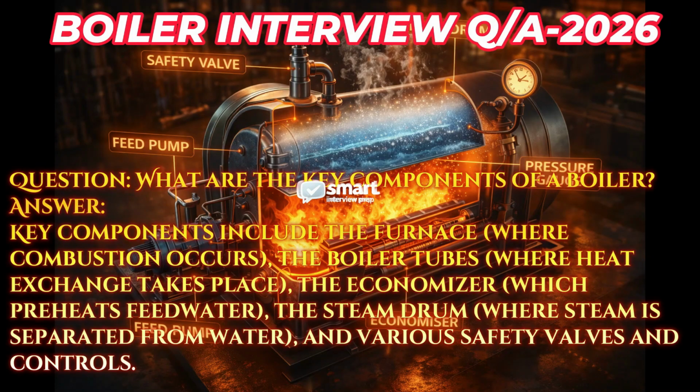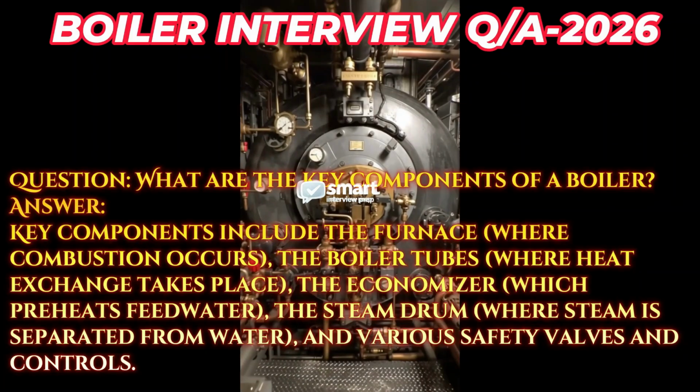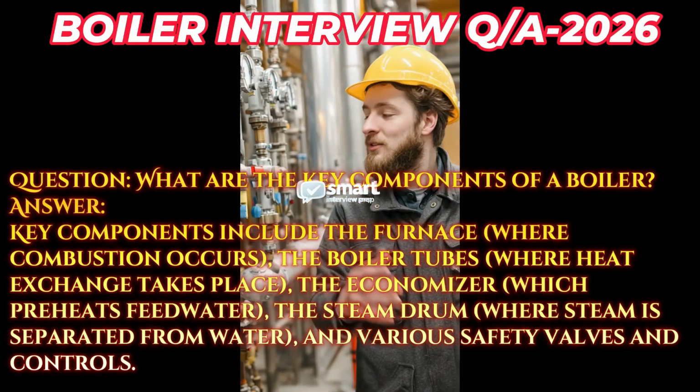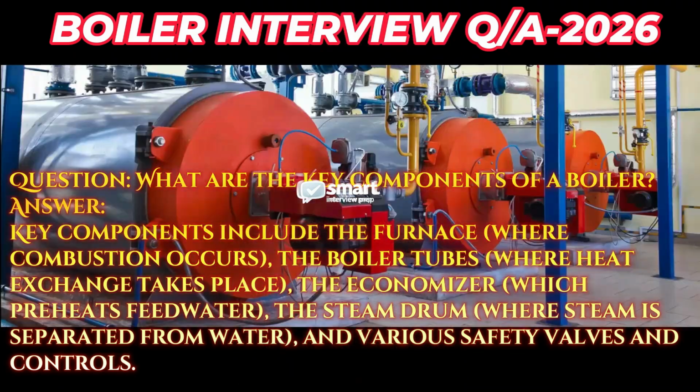Question: what are the key components of a boiler? Answer: key components include the furnace, where combustion occurs, the boiler tubes, where heat exchange takes place, the economizer, which preheats feedwater, the steam drum, where steam is separated from water, and various safety valves and controls.